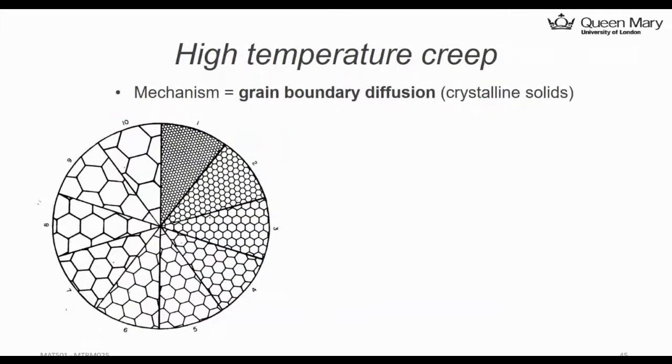Okay, so if you look at the left-hand side figures, for a certain material, they have different grain sizes depending on your material refinement. For one here, there are a lot of small grains, and 1, 2, 3 until 10, you have big grains, like hexagonal grains.